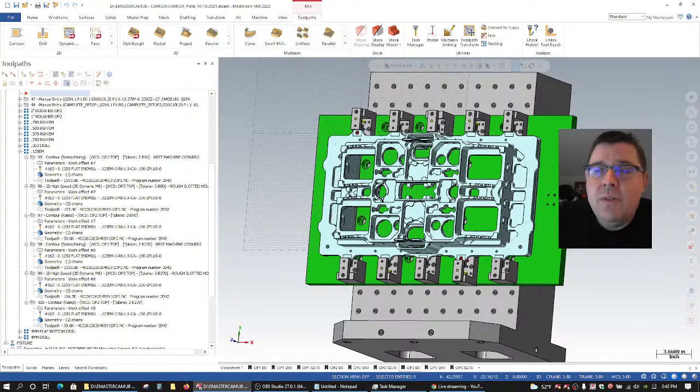So one of the things that can be a real advantage to you is to look at everything as a package. Ideally what you're going to have is a combination of a fast single core processor. And I'm not talking necessarily about only having a single core processor, but the most important thing for a Mastercam computer is a fast clock speed.